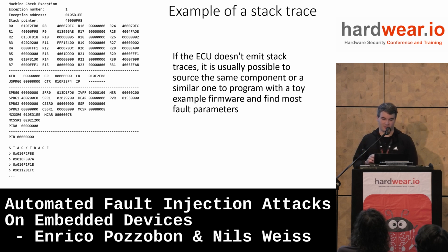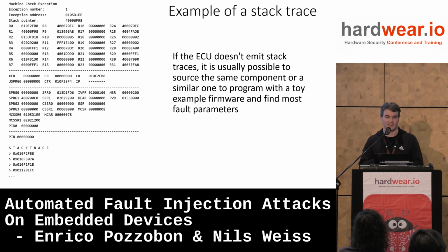Now, as I said before, not every ECU emits a stack trace like this, but it is usually possible to source the same microcontroller from an online vendor, flash it with our toy example firmware that does emit stack traces, and then we can train all of the parameters that don't depend on the software. We can train them on this chip. And later we only need to figure out the missing ones when we attack the real hardware.